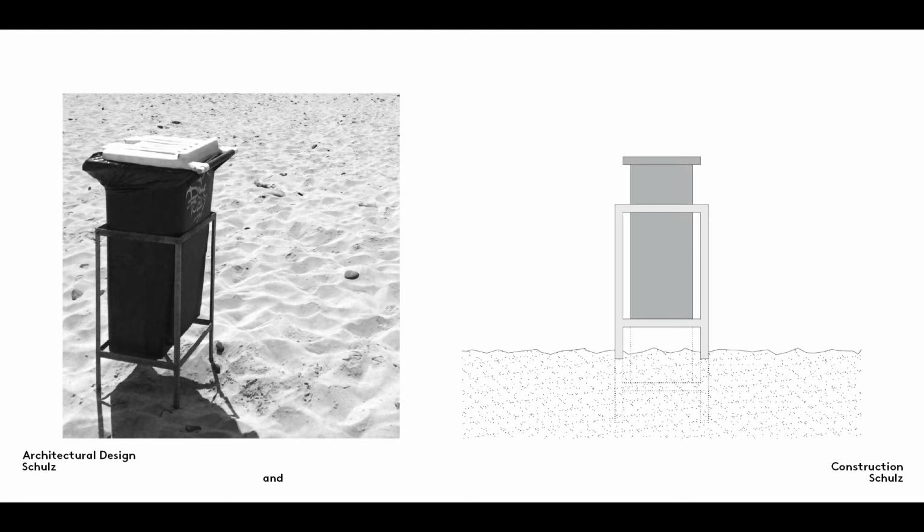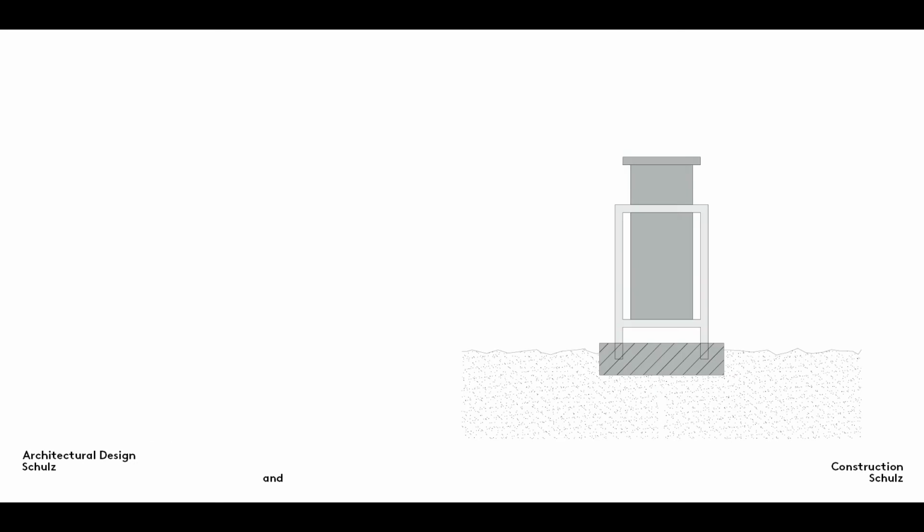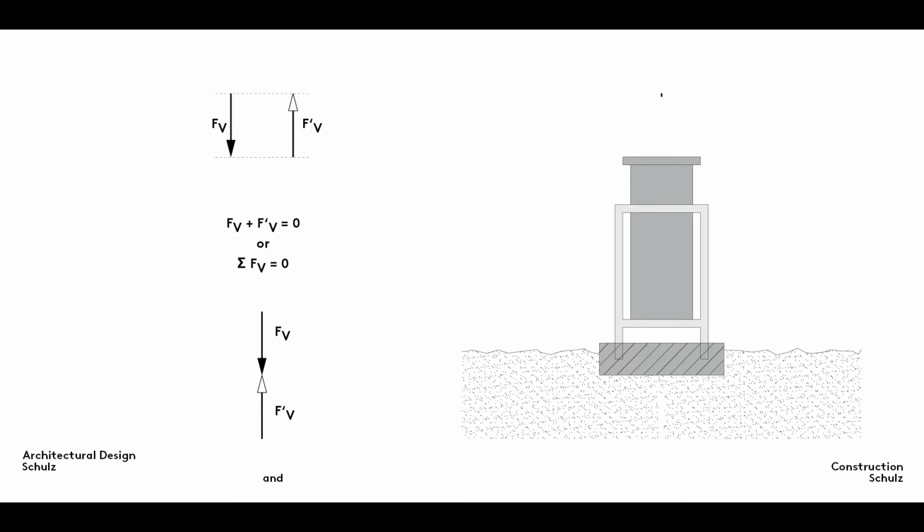buildings. This litter bin is in danger of sinking because the sand beneath it is unable to take its weight to push against it with sufficient force. The litter bin is more stable when the dead loads, the weight of the bin, and the live loads, the litter in the bin, are distributed more evenly over a concrete slab. The loads act over a larger surface area, and the sand, which makes a poor foundation, is better able to develop the necessary counterpressure. The force resulting from these loads acts against a counterpressure exerted by the sand.